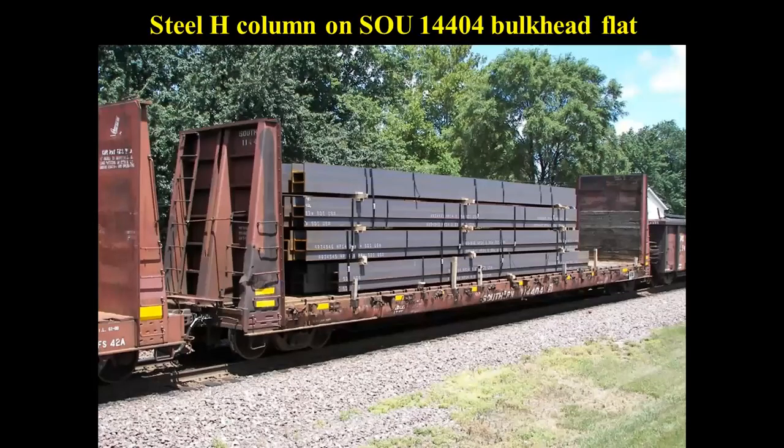Here's some H-column on a bulkhead flat car. Again, you'll see that in addition to the pieces being nested together, they're also banded together with steel banding. There's blocking between the layers, and there's even 4x4s stuck into the stake pockets to prevent the load from shifting.